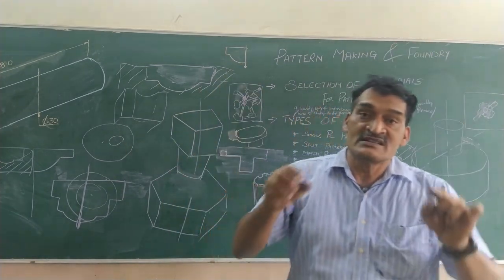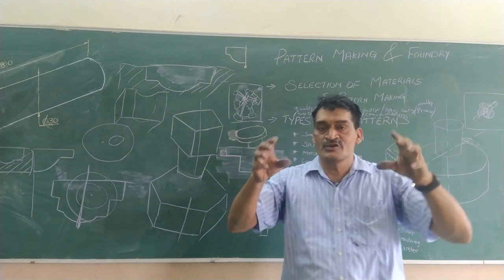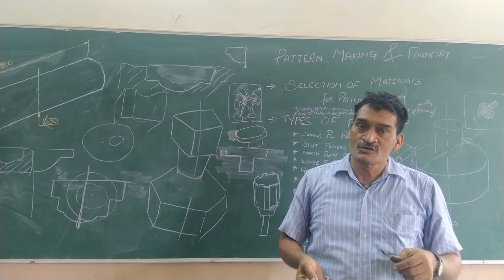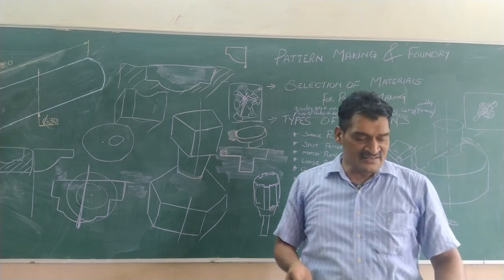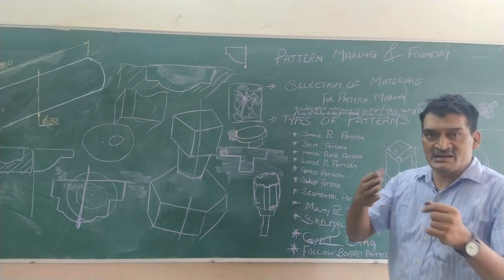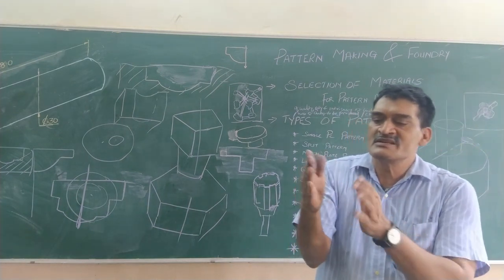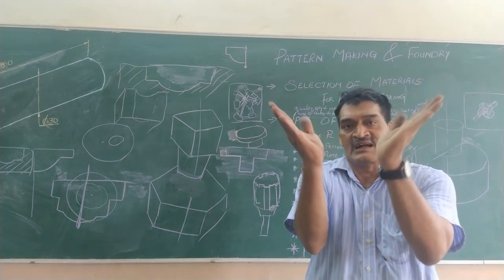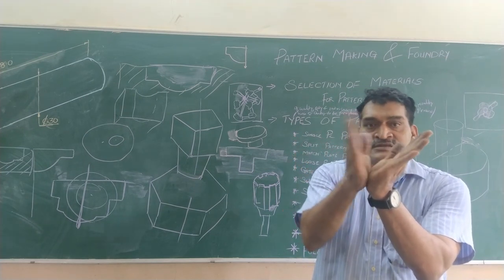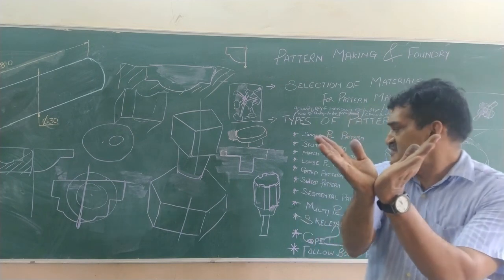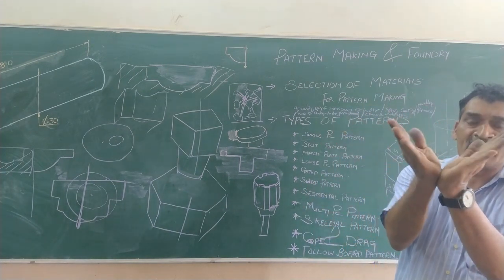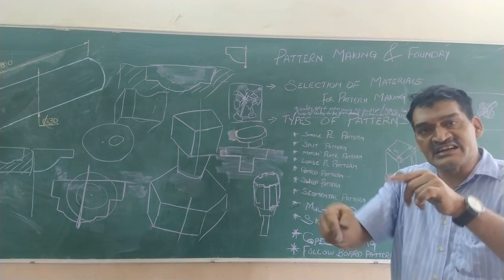Okay, so now these spokes, you want a casting to be made of that rim. So what we do is, first, just like a sweep pattern, we make a cardboard. We sweep in small angles in a circle. So we sweep in small sectors. So when you sweep in small parts, it is called a segment.